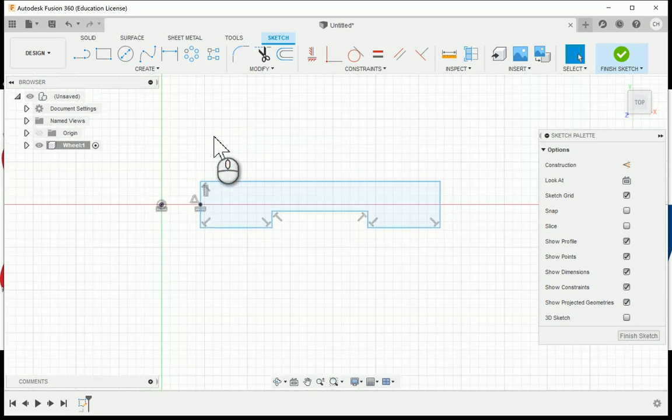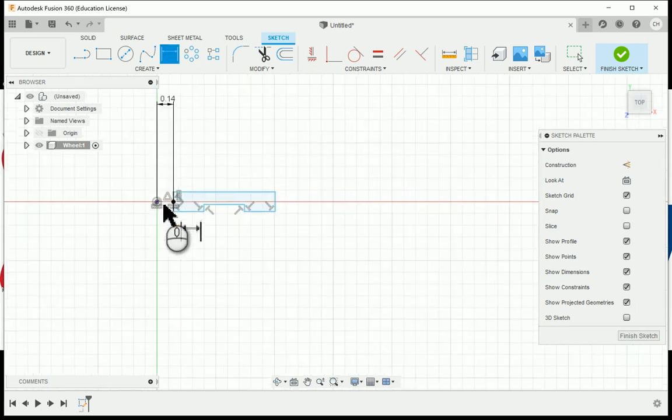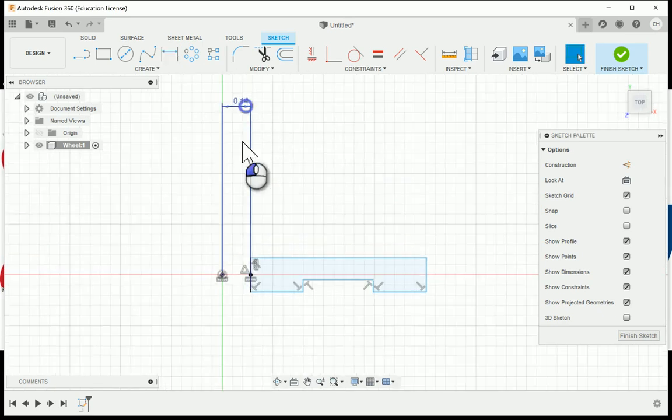So as noted by the drawing, from the center here to this first line, we're going to leave a space open for the hole. Now the hole is going to have a diameter of 0.280, and since we're going to do a revolution, a section, we're going to divide by 2, and I'm going to hit enter. So that's going to size our sketch down, and I'm going to bring that dimension a little closer.